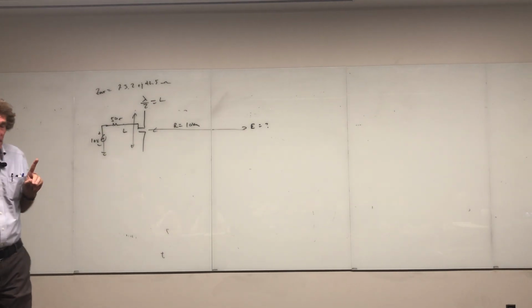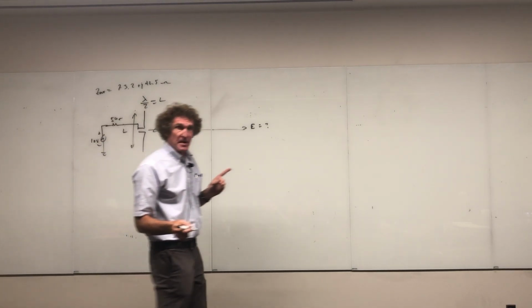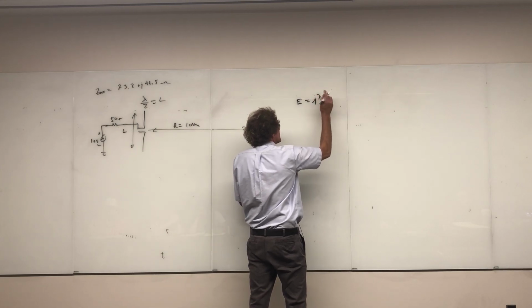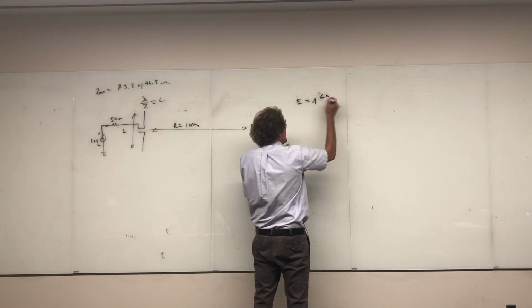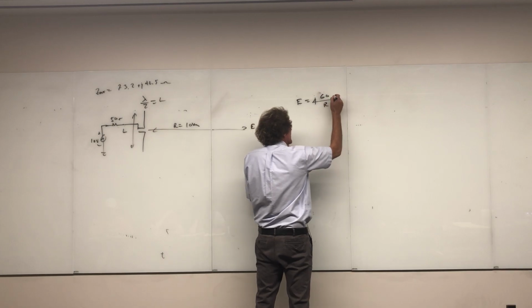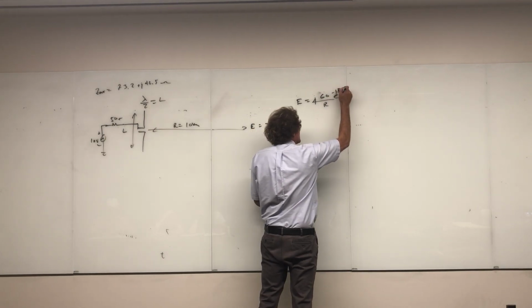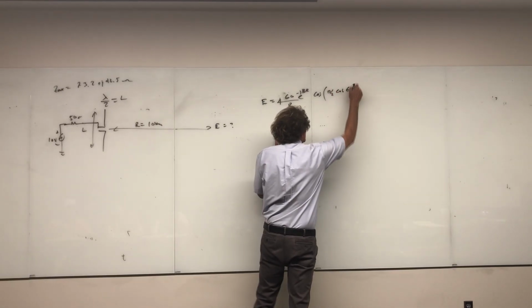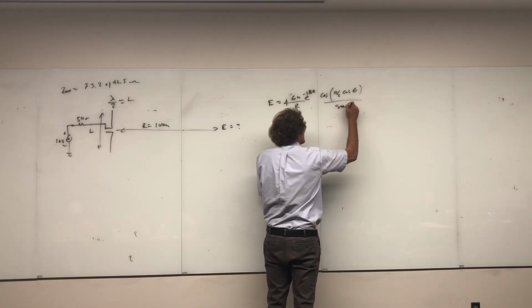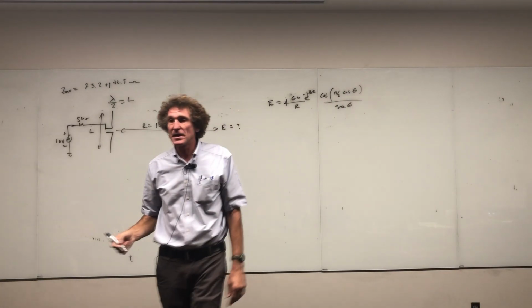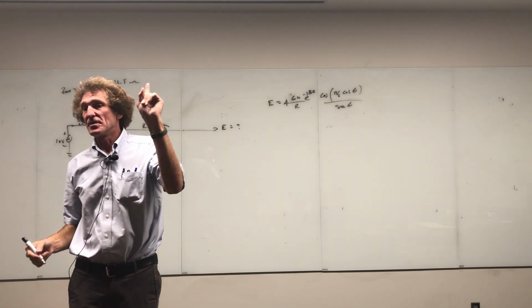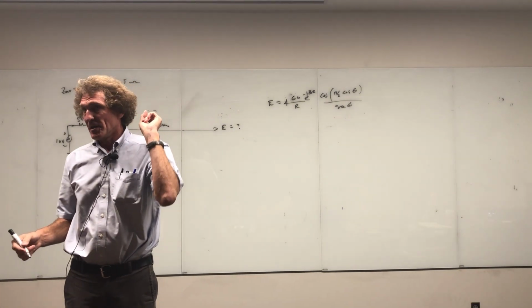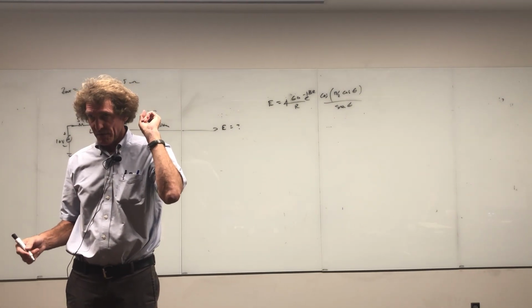So the first way is the basic equation for electric field from a half-wave dipole, which is just equal to j60 I over R times e to the minus j beta r, then times the cosine of pi over 2 cosine of theta over the sine of theta. Now that's an angular function, but when theta is 90 degrees, that angular function is 1. Do you follow me on this, class? The cosine of pi over 2 cosine of 90 degrees divided by sine of 90.